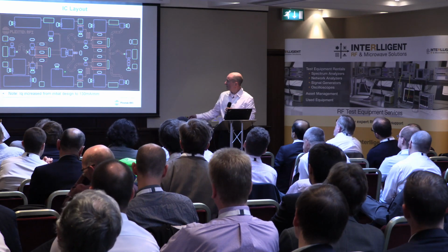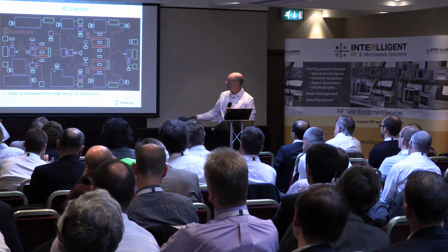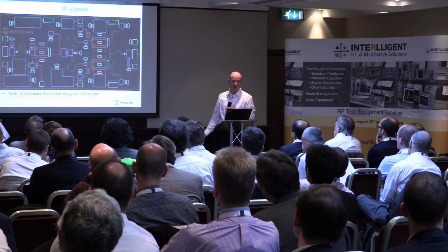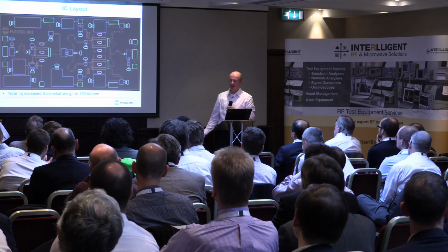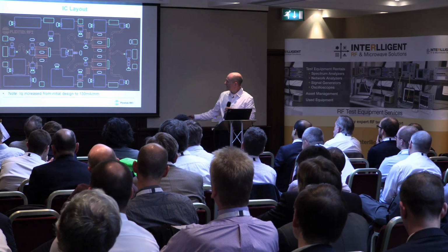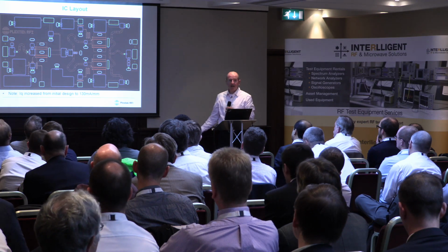You can see here we have decoupling, a different shape. We just had some more space, so we put in a different shape decoupling capacitor to fill the area. It's expensive per unit area, so we make use of it. This is a parallel RC, and that's quite a nice way of improving stability. What this does is it presents more loss at the lower frequencies where the C is a higher reactance. And we have a similar parallel RC here.